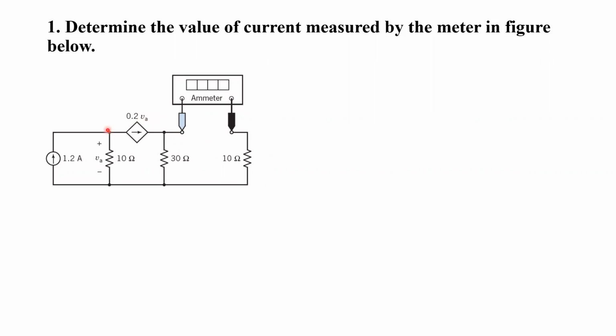So we'll first start by applying KCL at this first node. First of all, we'll create a ground node here, and the voltage of this ground node will be equal to 0. We're assuming this node as node 1 and this as node 2. Other than current sources, in the case of all the resistors, we will always assume that current is flowing out of the nodes. That means it will always give outgoing currents.